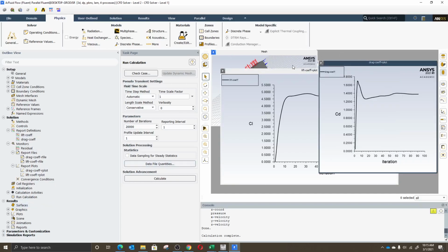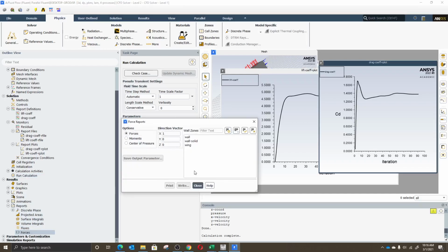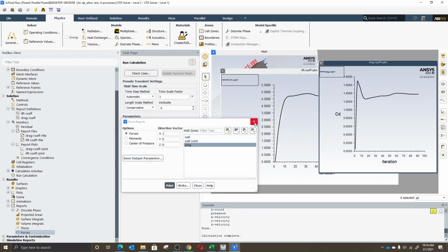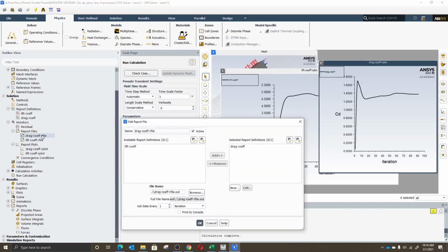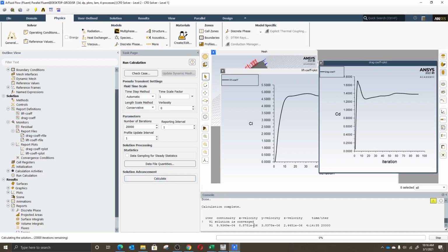So these are your results. We have lift coefficient and drag coefficient for one angle of attack. We can actually submit reports for forces here as well. Create reports for forces in a text file. And on a wing, let's see, same thing, forces in the X direction, wing, you want to write it to a file, anywhere, it will give you the lift coefficient, and each iteration you want it only use the final value. You can actually double click on this to get the lift coefficient as well. It should have given us the lift coefficient. Then you click on calculate, it will give you the